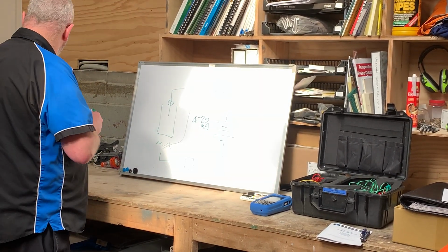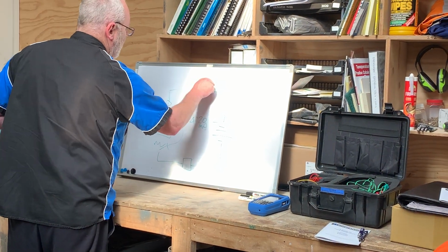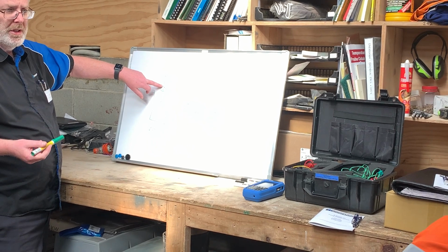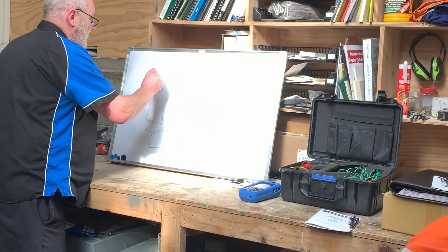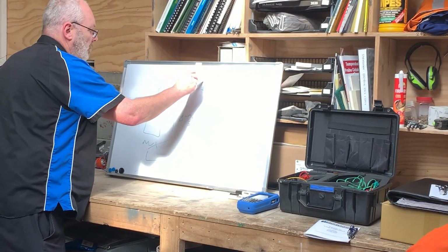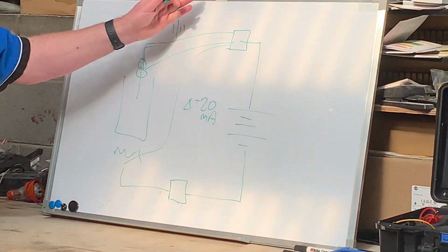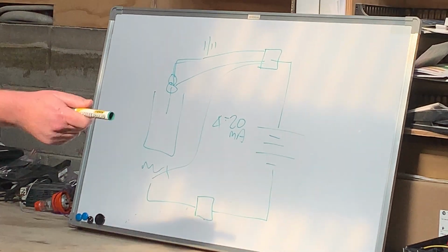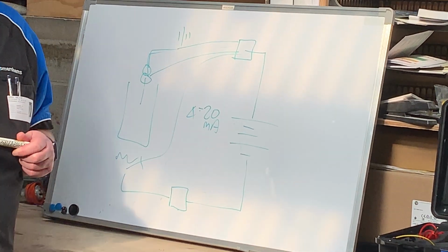Now, of course, as you probably know, in the real world, you might have another transmitter in the head, especially if it's going over a long distance. So let's say there's another transmitter in here. So there's actually a second 4 to 20 milliamp loop on that input side. All makes sense so far? And I've drawn this much more nicely. You've got booklets there so you can look at it later on.